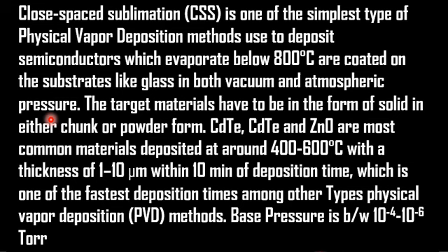Then the gas molecules of the precursor material will collide with each other. Due to this, it will result in impurities and defects in the deposited thin film because of the collision of the precursor gas molecules. So dear student, the closed space sublimation process, or any vacuum based process for depositing thin film, is preferred to be done at low pressure as compared to atmospheric pressure or high pressure.